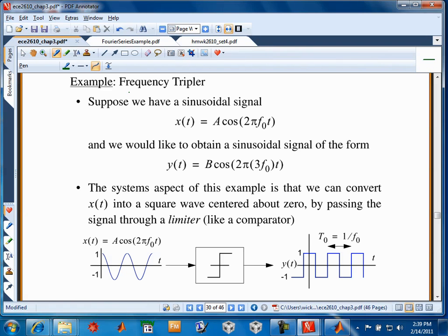You can think. A phase lock loop synthesizer could do that, but a way of doing that with passive electronics would be this idea of a frequency tripler. The tripler multiplies the frequency by 3. And in radio frequency circuits, a lot of times you generate from a standard clock a higher frequency signal using some nonlinear processing block, such as this tripler. It's connected with the idea of frequency synthesizers, though, too, where you'd use something called a phase lock loop, which gives you the digital tuning capability that most radios have today.